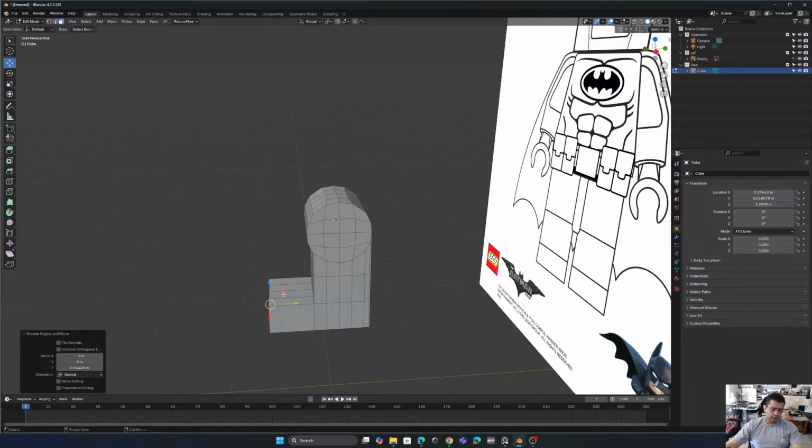I want to create some cuts here to help us preserve the shape when we smooth it. So I'm gonna press 2 to go to edge mode, or I'm gonna press over here edge. Ctrl R to make a cut. I think with 2 it's gonna be okay. Click to place it, and then I could move it. I don't want to move it, so I could press escape, and it's gonna place it just in the middle of the edge.